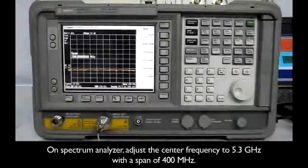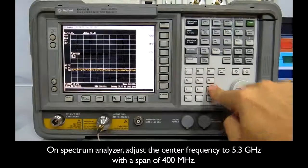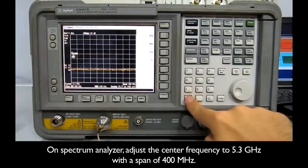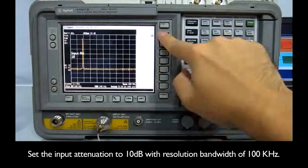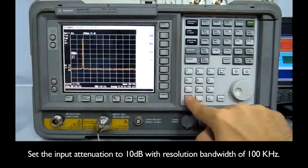On the spectrum analyzer, adjust the center frequency to 5.3 GHz, with a span of 400 MHz. Set the input attenuation to 10 dB, with resolution bandwidth of 100 kHz.